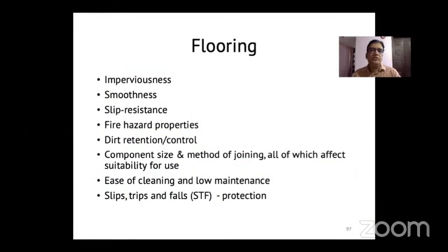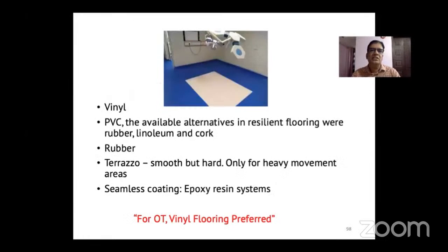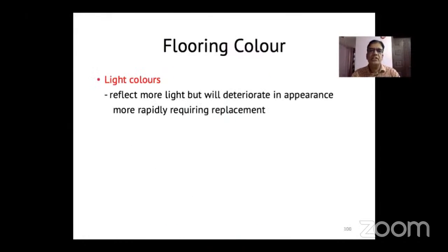And a little bit about the flooring. Any flooring which is used in the operation theatre should have some important characteristics with respect to its imperviousness, smoothness, slip resistance, fire resistant properties, then dirt retention and control considerations, then ease of cleaning, low maintenance, and slips and falls protection. So generally, vinyl, PVC, rubber, terrazzo, and epoxy resin systems are all available, apart from the hard stones which were used previously. But generally, for OT, vinyl flooring is preferred.